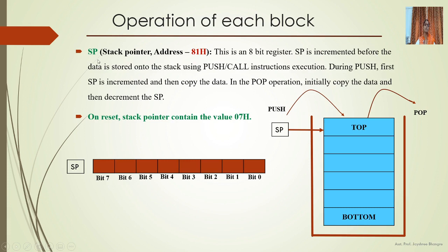Next important SFR is the stack pointer. This is used for stack memory. So stack refers to an internal RAM used to store and retrieve data quickly, and the stack pointer is the register used to hold an internal address which points to the top of the stack.